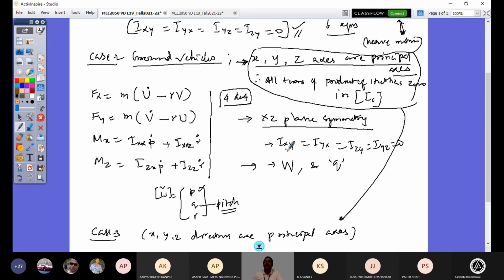And of course, W is not there. You should not misunderstand bounce motion with this. Bounce motion is a local motion in your vehicle, right? That is to study your vertical dynamics alone. But that does not make your vehicle come out of the ground. The vehicle has always been in contact with the ground because of your suspension system. So there is essentially tire dynamic deflection present, as we have studied. So these 2 motions are neglected.